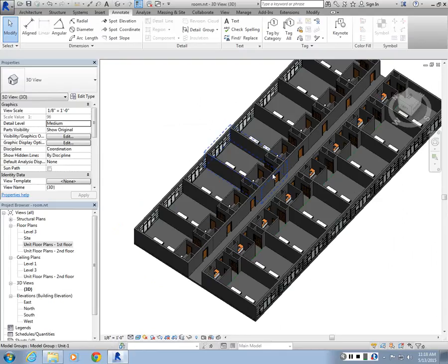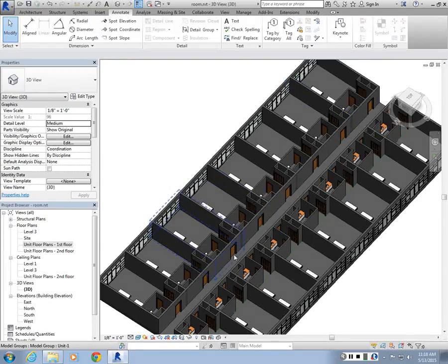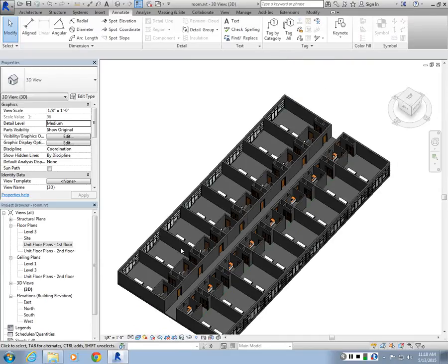Job done. Right? So why did I do the groups before I made the copies? Because if there's a modification I wanted to do to the furniture layout of the room, or to the wall configuration, or anything I want to change, you don't want to do this operation afterwards, right? You want those smart objects to be cross-referenced and copied so that when I edit one group, all of the instances would benefit from that modification as well. So they will get whatever is added to the group.